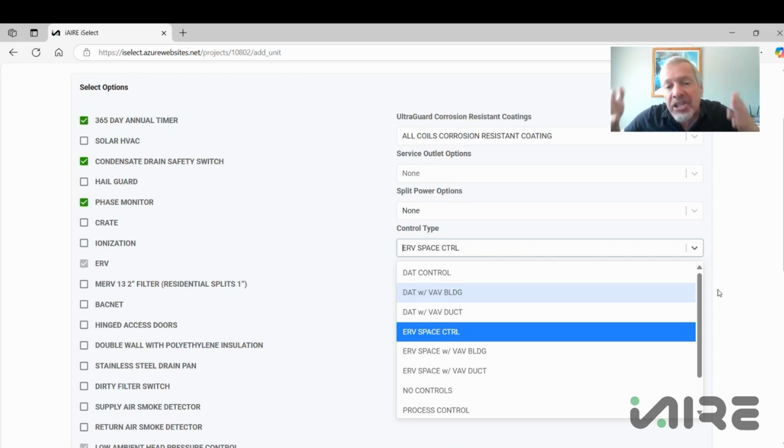In fact, that's actually what people are doing when we build a unit to deliver neutral air to a space. That is discharge air control. We are setting a discharge air temperature. Remember, that's the temperature of the air out the end of the unit. That's after that air has been processed by the unit at all points.